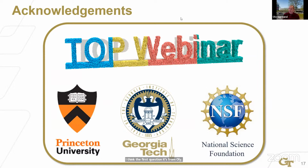Sure, thank you for an interesting talk. I was just curious, is spinodal microstructure guaranteed to be open-celled, or could you have cases where there's an enclosed cavity? So that's a great question. It depends on the spinodal density, and that's why we chose this range of 0.3 to 0.7 density. In this range, we can guarantee that we will not have closed cavities or disconnected components. If we go below 0.3, we can have disconnected components, and if we go above 0.7, we can have closed cavities that can hold resin during 3D printing, so that's not good.